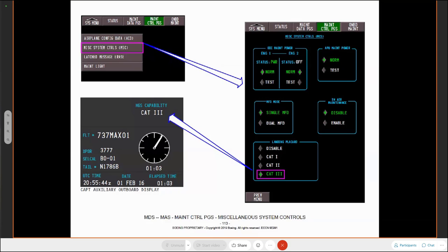However, once the aircraft passes 10,000 feet, these will now be selectable, and the crew can look at those maintenance data pages and so on, and they can take manual records. They can send that information down to the ground station and back to the base. If you put it in disable, then as soon as the aircraft takes off, you can't access any of that information.